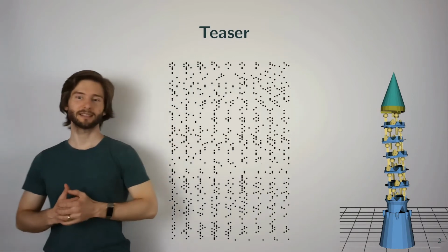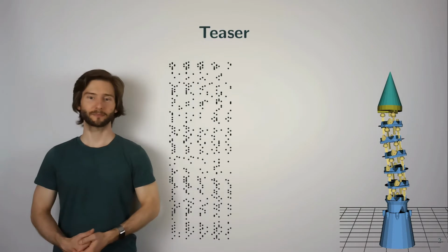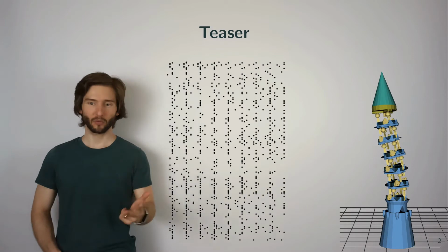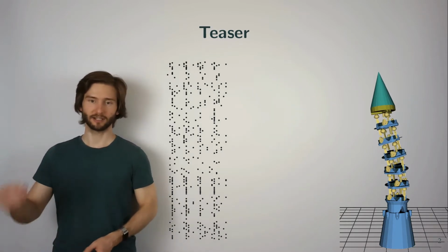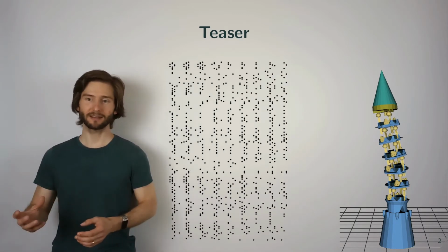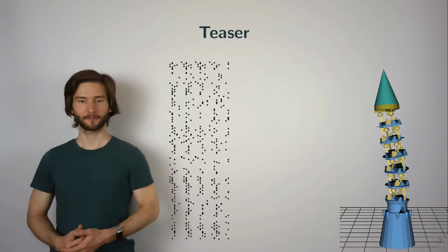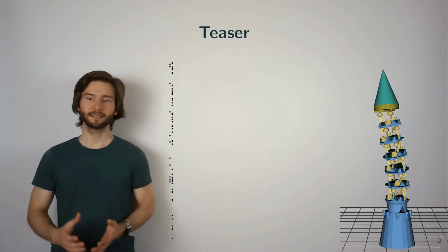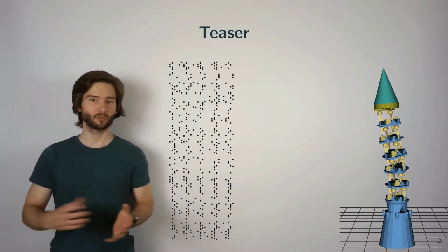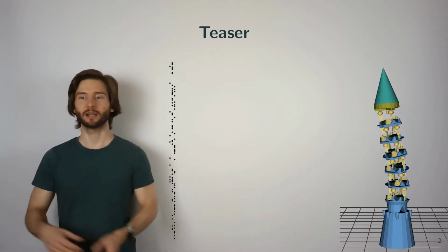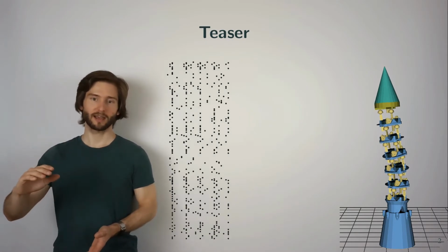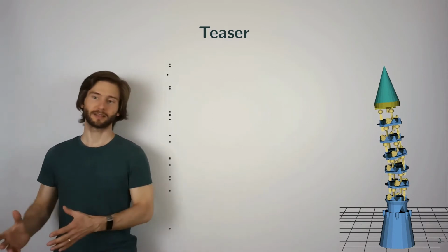Here on the right you can see a simulated 6-joint robot arm, and the movement of each joint in the simulated robot is controlled by 3 servo motors that each drive a linear gear. And each of those linear gears is connected over a ball slider mechanism with the base of the next joint. And by now adjusting the linear gears, a joint can approach any combination of tilt angles along the x and y axis in the range of -40 and +40 degrees. And additionally, a joint can alter the distance to the next joint, whereby the approached angles limit the movable distance and vice versa.